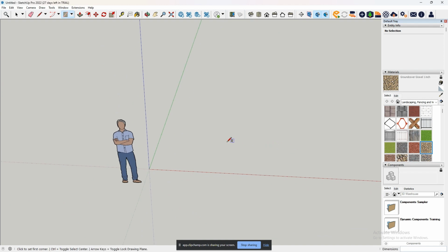And you can do that typing in with pretty much any of the tools. I'll do it again with the line tool, for example. If you wanted to measure a line to be a specific length, it's probably not best to do it on the red line there, but if you were to do it here, you can see as I'm moving it, if you look at the bottom right hand corner, the length is moving up and down in millimeters.